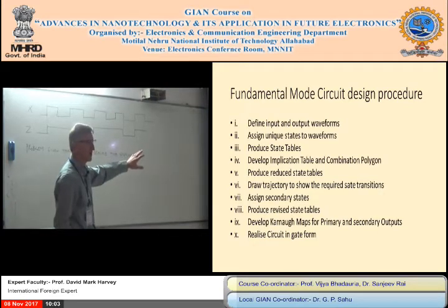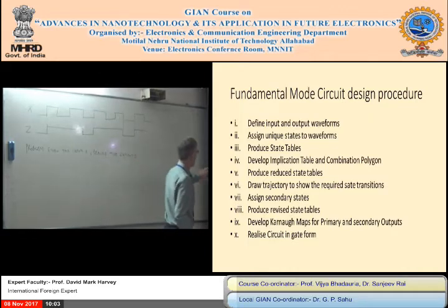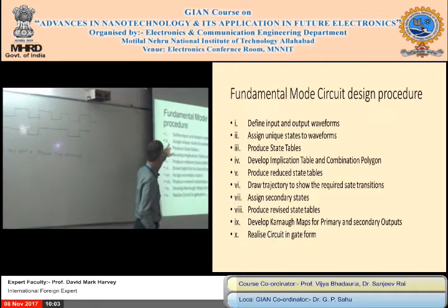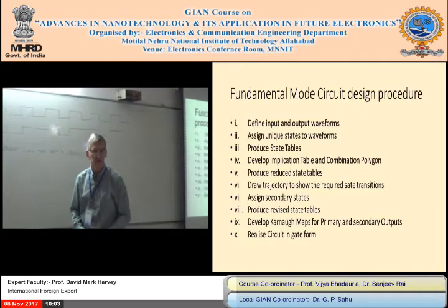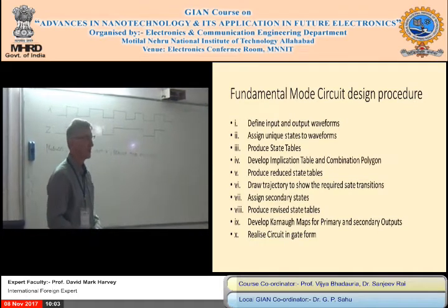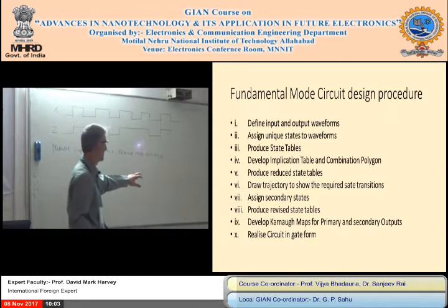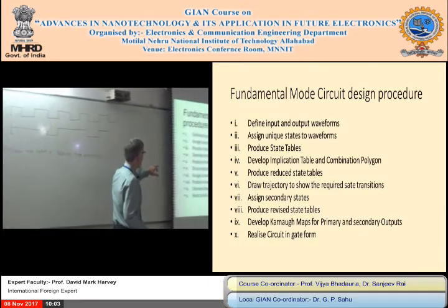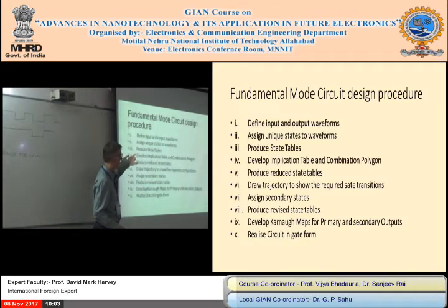So I've put up the circuit design procedures on the slide there for this type of circuit. So number 1, we've defined the inputs and outputs. As engineers, you might have to do that for yourself. Or in this case, I've given you the design spec there. Okay? So the hardest part of this is the next part, which is number 2 on the list. Assign unique states to the set of waveforms.